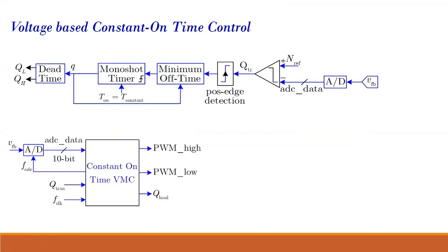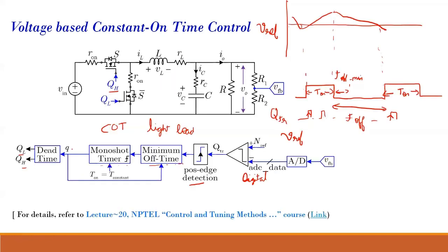Now, how will we implement this waveform? Yes, this one which you have drawn is the Q waveform, the small Q. Then afterwards you add your dead time and correspondingly you get QH and QL.